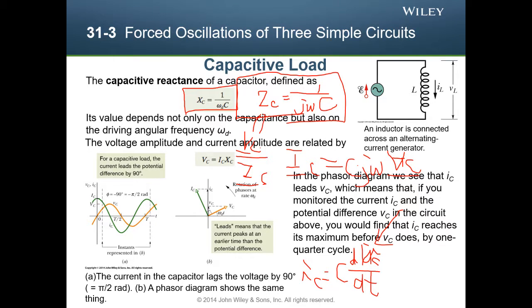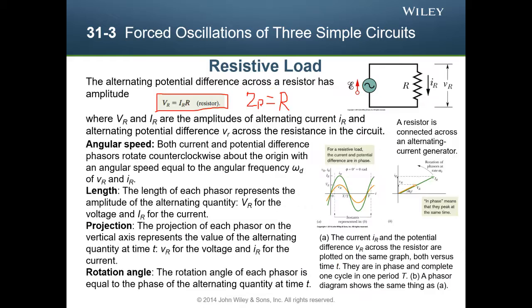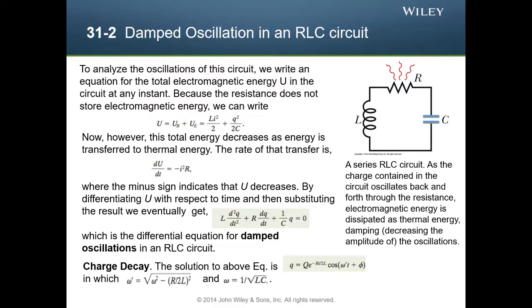And with the phasor, you can calculate the RLC circuit more simply. But using this method, you cannot calculate the homogeneous solution or the transient response. You can only care about the steady state response, because usually for the second order equation, if it is stable, which means that this term will have a negative coefficient for the exponential function.